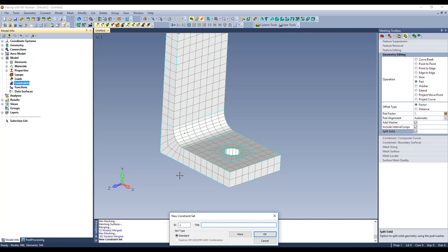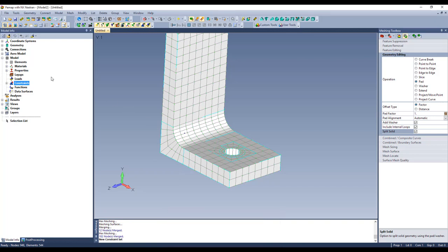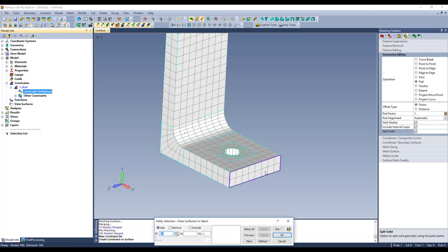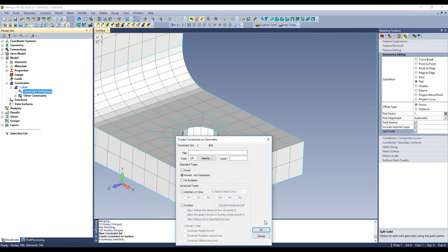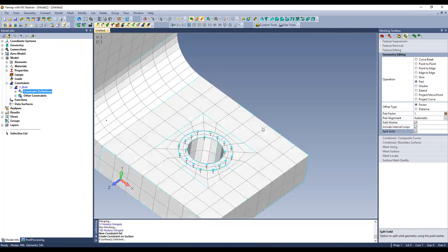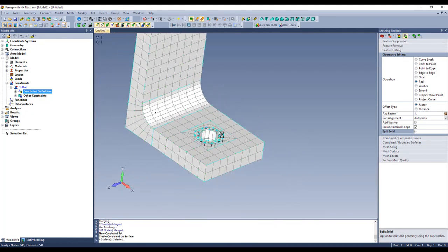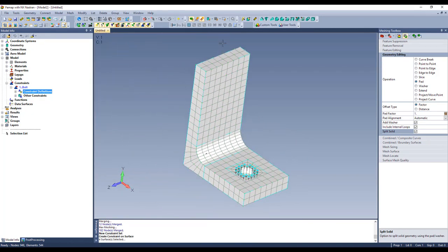And I'll just say, let me simulate a bolt head holding this thing down. So this will be a pretty simple constraint. So we'll say on surface. We'll go pick those 4 and just say pin this thing down. We could get into bolt preloads and stuff, but perhaps we'll look at that later. And we'll just pull up at the top here.